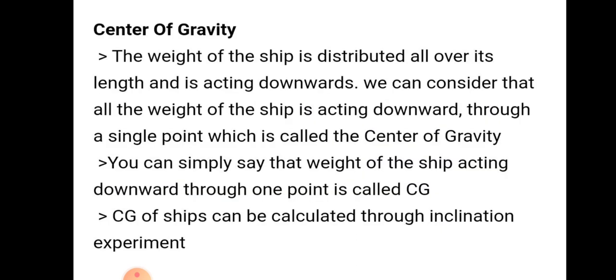Center of gravity means the weight of the ship is distributed all over its length and is acting downwards due to gravity. We can consider that all the weight of the ship is acting downward through a single point, which is called the center of gravity. Center of gravity of a ship can be found out using the inclination experiment.